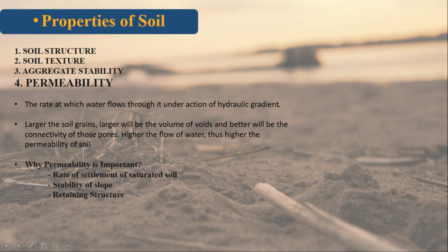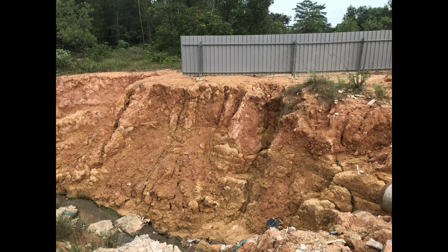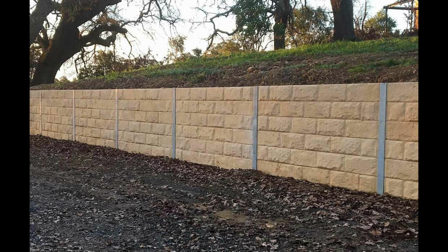Permeability is important in geotechnical design as it influences the rate of settlement of a saturated soil under a load. For example, the stability of slopes and retaining structures can be greatly affected by the permeability of the soil involved.